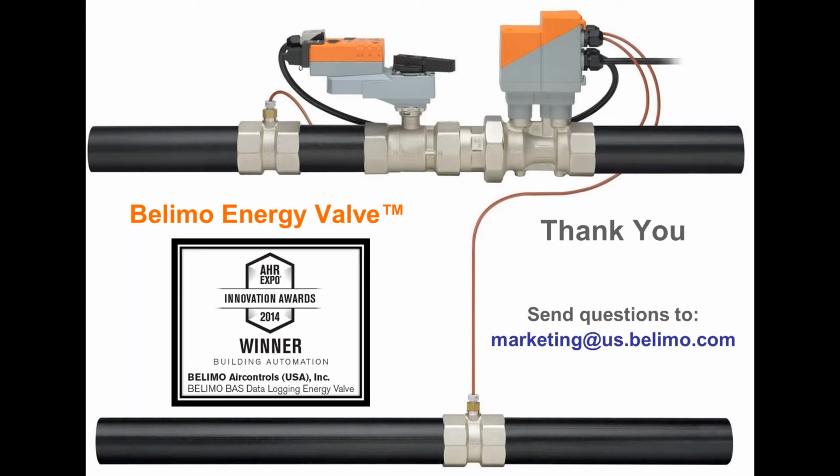There is a Cat5 plug on the back side, and the actuator has a contained web server. So it has an IP address, and you can basically log into the actuator and program all your parameters. Most of those parameters can also be programmed directly through BACnet, so you could do that through your automation system.